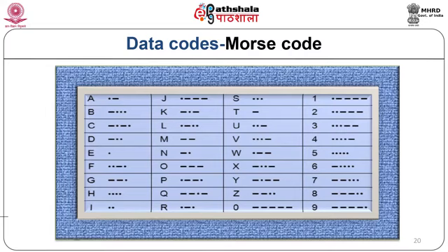The telegraph key, when depressed, causes current flow in an electromagnetic coil that attracts the armature and releases it quickly when the current stops, making clicks during both the instances. When the armature is closed for a short duration, a dot is produced, and when closed for a longer time, a dash is produced.